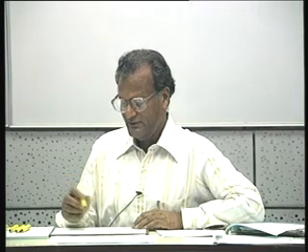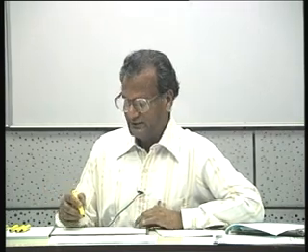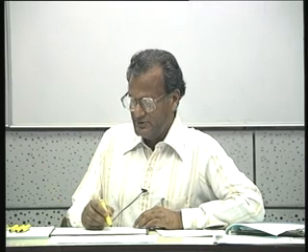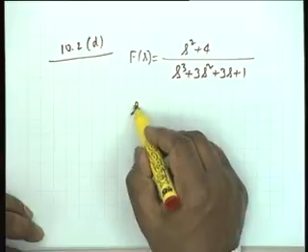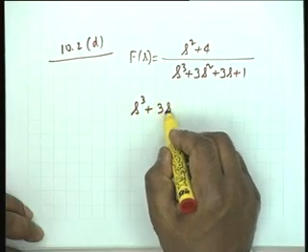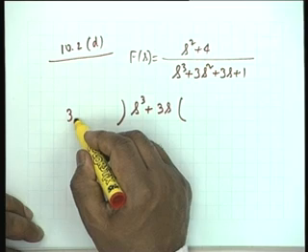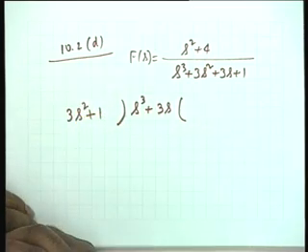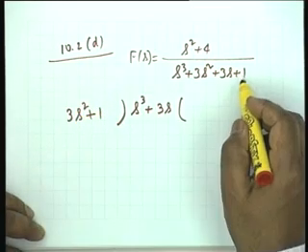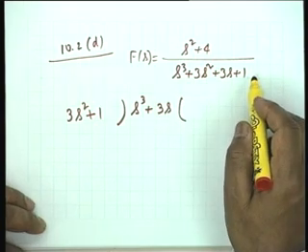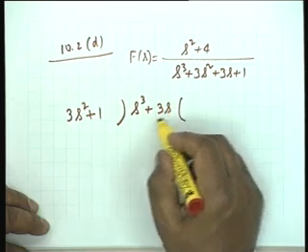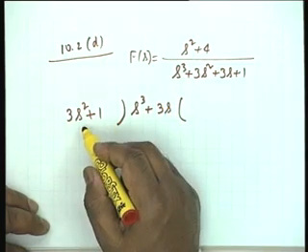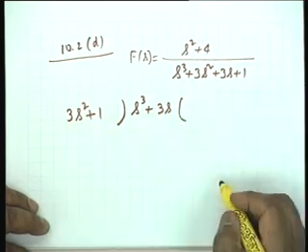First, it is obvious that f of s is real when s is real. First part is okay. Now to see whether it has right half plane poles or not, we must make a continued fraction expansion of s cubed plus 3s divided by 3s squared plus 1, right? We must check d of s, the denominator polynomial, whether it is Hurwitz or not, and for that we take the higher power term, that is the odd part, divide by the even part and find the continued fraction expansion.